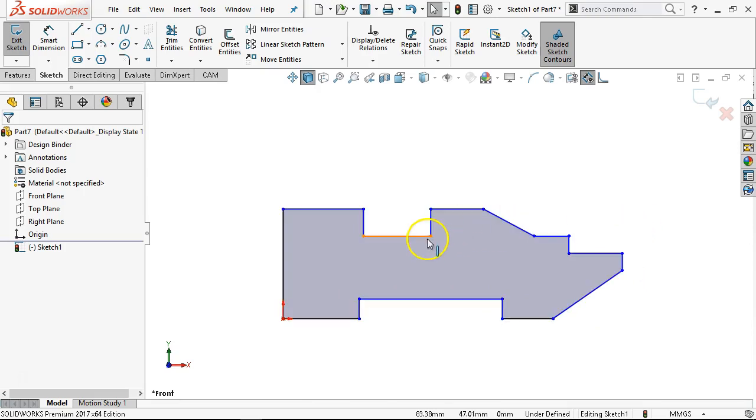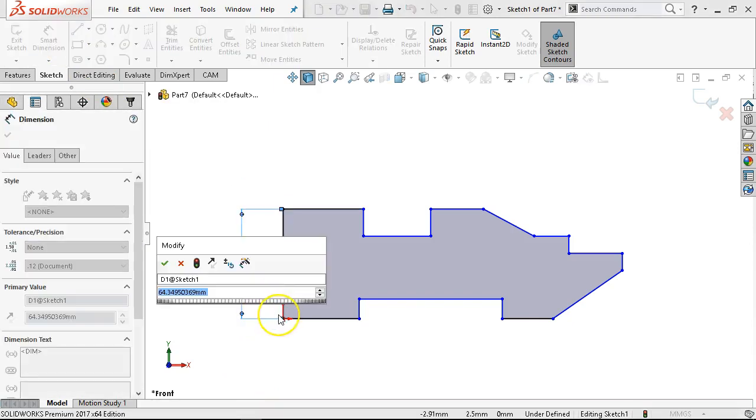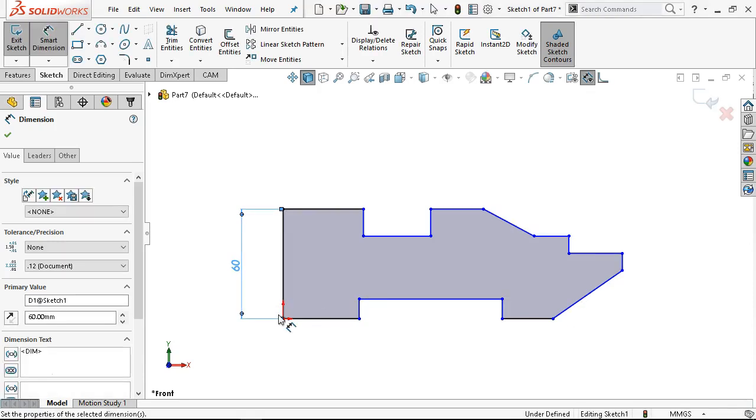So in contrast, I'm going around the perimeter because in certain cases it's going to be more complicated. If I just drew these first 4 or 5 lines and got them to go fully defined, and then the next 2 or 3, that may make it more manageable. But I know the tendency is I see a shape, I want to create that shape. All right, so just be aware that some of the shapes that you get into as they get more complex, you may want to break it into smaller, more manageable chunks.